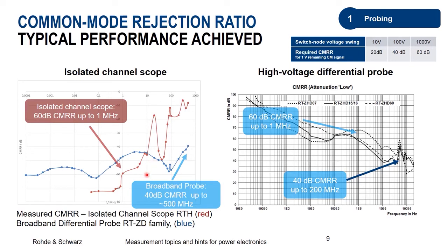The other thing is, when you look at broadband probes, you find out that sometimes they might be very interesting for power electronics applications, in particular if the voltage swing is not so high. Broadband probes are usually available only for ±5 volts, but there are models that accept an additional external attenuator, which makes them usable for a voltage swing of up to ±50 volts. And if you consider the additional offset, you can theoretically measure from 0 to 100 volts with a broadband differential probe.